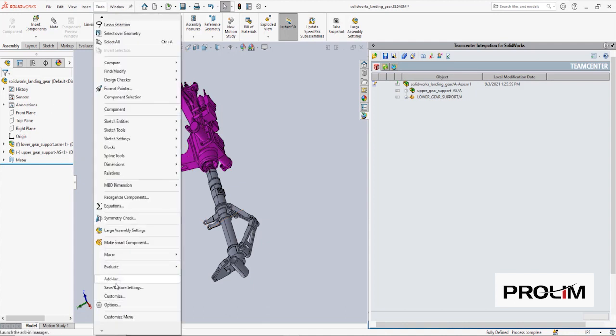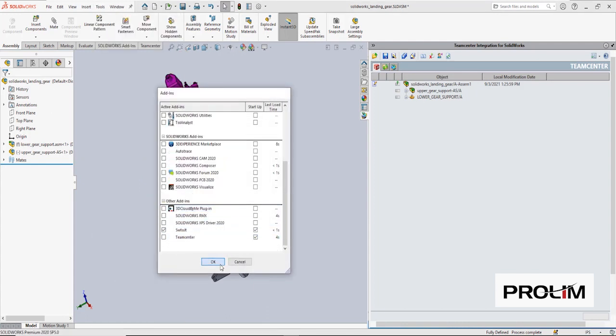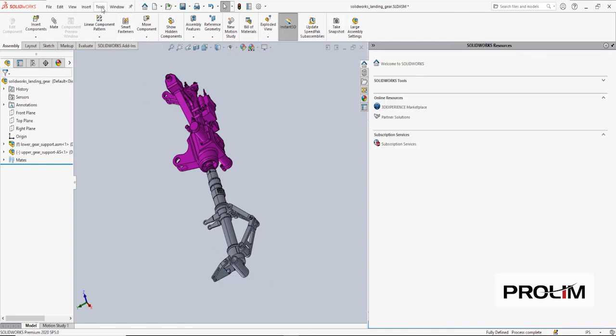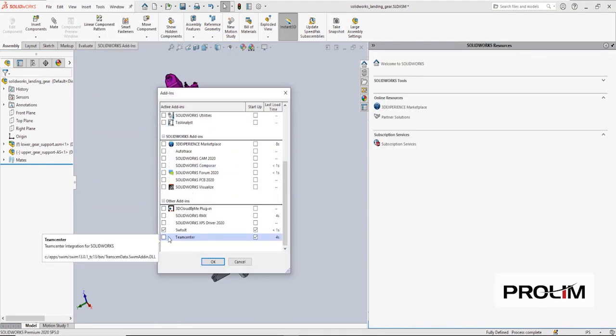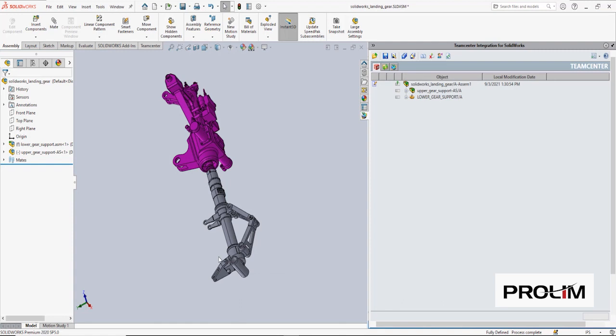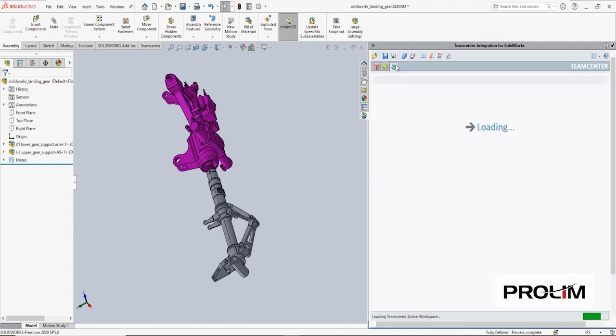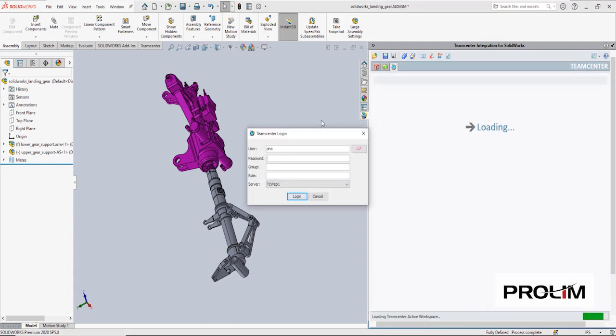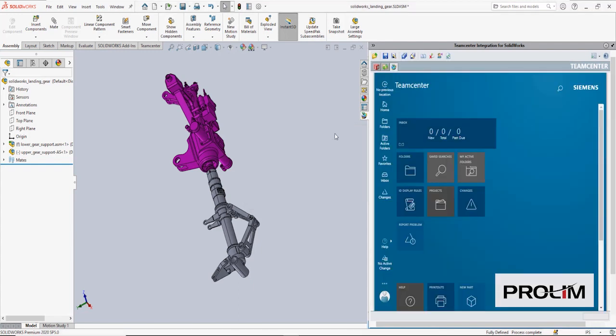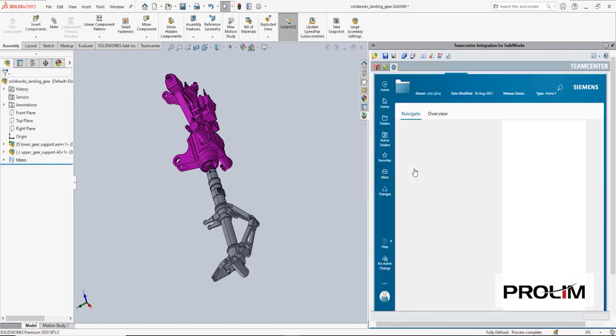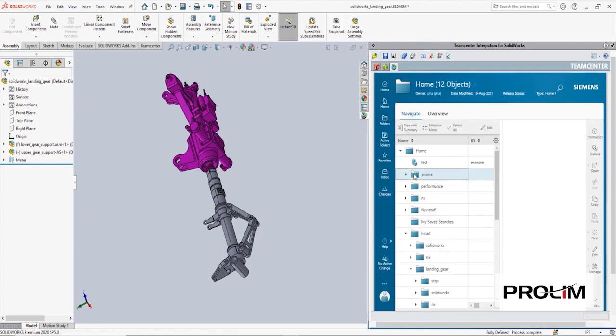After logging out and back into Teamcenter, we can try once again to insert the Inventor assembly. This time, because of the configuration changes, the integration will find and use the JT part files instead of the native Inventor files. It will build a transient SOLIDWORKS assembly with the JT files, using positional information from the Inventor assembly's bill of materials.